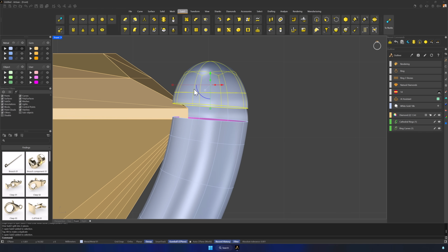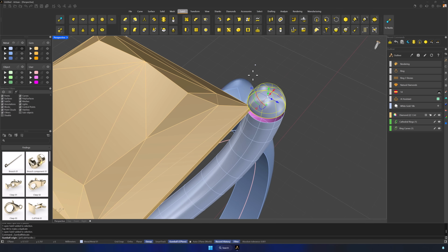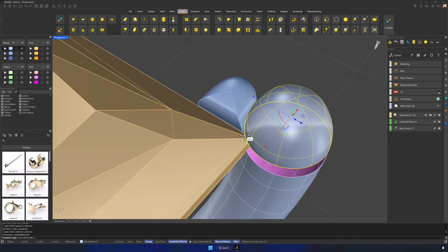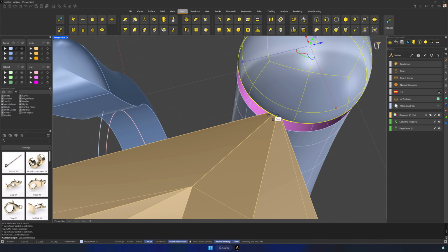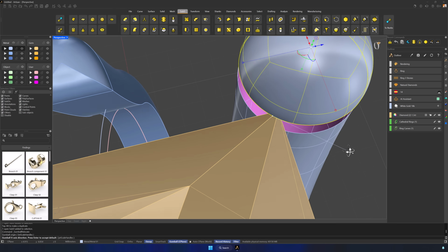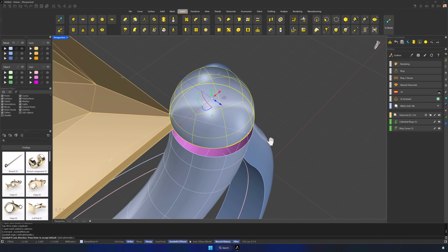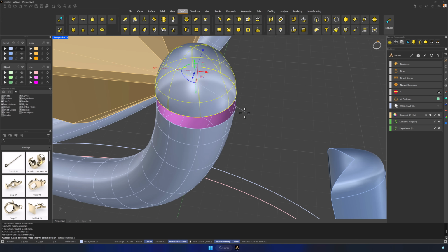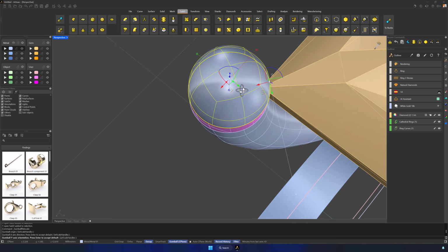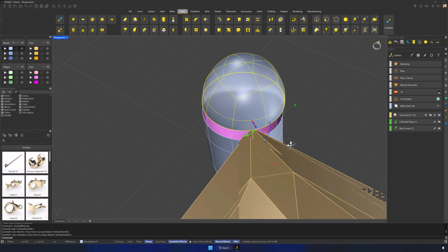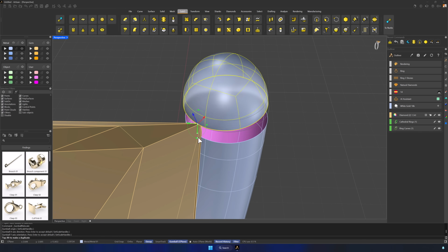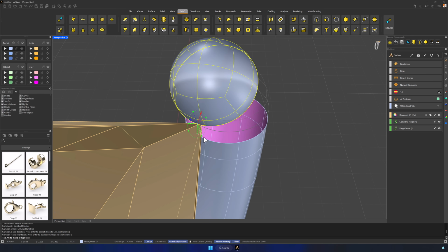Next, select the extracted part and click the small sphere on the gumball to choose Relocate. From the perspective view, select the point that's approximately centered with the gem. This will be the pivot point for rotation. Then, click on the back of the object and finally select the left side. This repositions the gumball so we can rotate properly around the gem. Rotate it until it matches the position shown in the video.